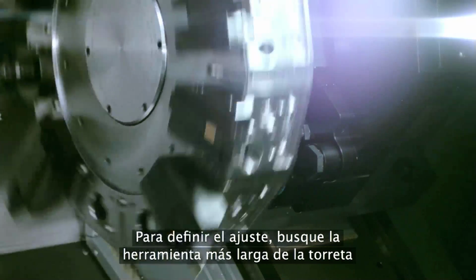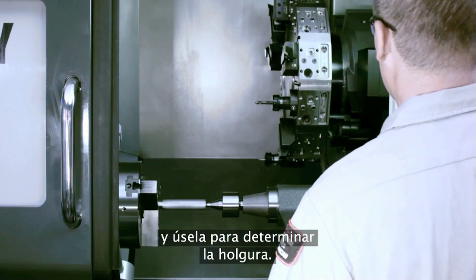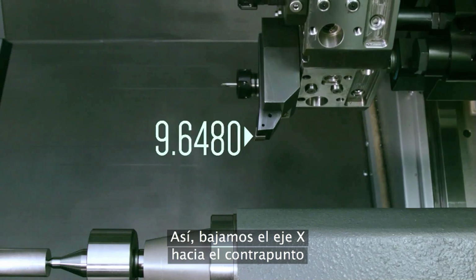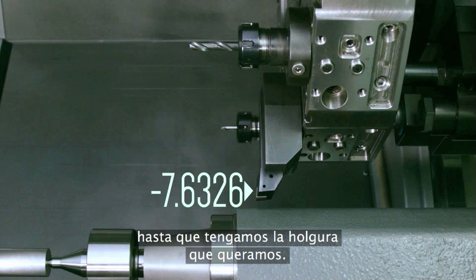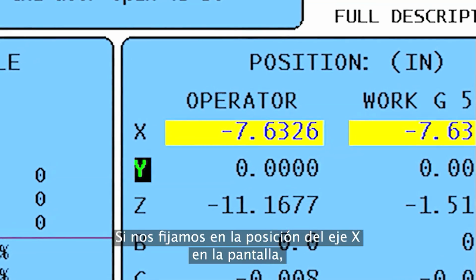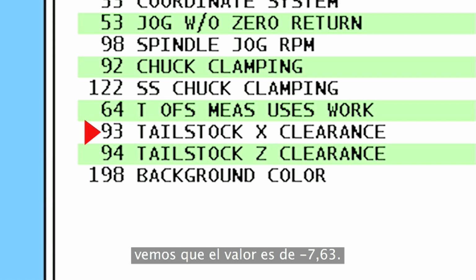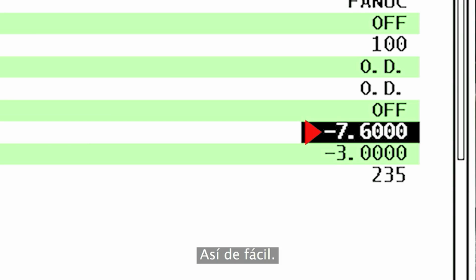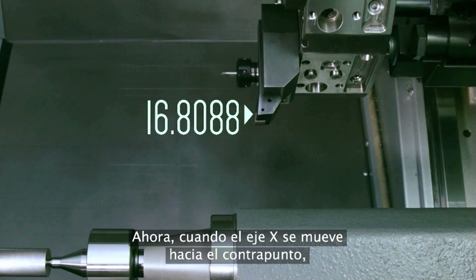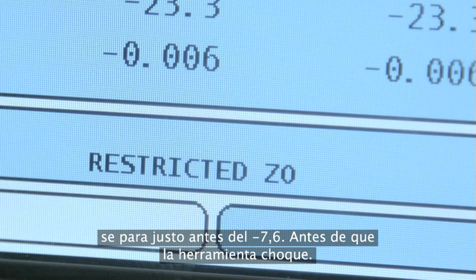So to set this value, find the most extended tool on your turret and use that to check your clearance. So we jog the x-axis down towards the tailstock until we find the clearance we're happy with. Looking at the x-axis position on the screen, the reading is x -7.63. So we'll change setting 93 to a slightly smaller value, like -7.6. Simple. Now, when x-axis motion moves toward the tailstock, it will halt just shy of -7.6 before the tool can crash.